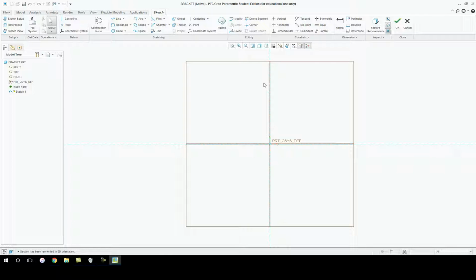Now I'm going to start this by drawing the bracket part of it, and then I'll go in and put in the circular part after that. So I'm going to start this one just by drawing my first two lines. That way I can get a reference for the actual size of the parts. So we'll draw the first line in over here, and then we'll come down. And I'm actually going to have to draw a little bit more than just those first two lines, because I want to make sure that I can get an overall dimension in here to kind of control everything else.